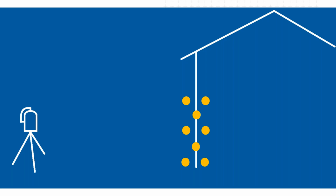The big difference is with scanning, you take the average to find where the true object is instead of relying on one single point. Because of that, standards haven't been written specifically for laser scanners yet. They've been written for total stations and trolleys and measuring tapes, but they just haven't got around to writing standards for laser scanning yet. The main point here: laser scanners, although very similar to a total station, are actually quite different in how they operate.